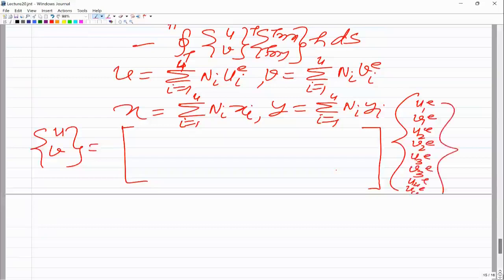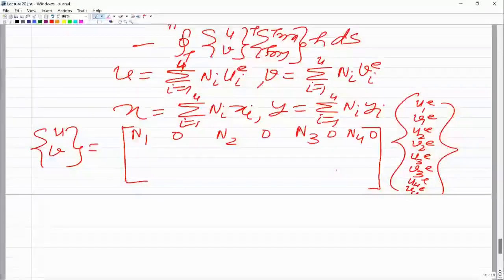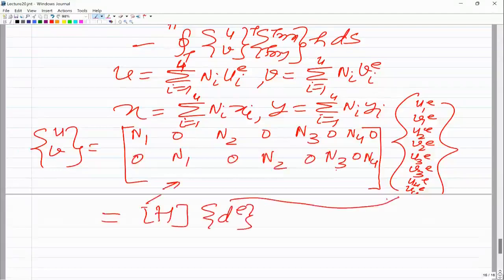And U is N1 U1E plus N2 U2E plus N3 U3E plus N4 U4E. So we should have N1, 0, N2, 0, N3, 0, N4 and 0. V is N1 V1E plus N2 V2E plus N3 V3E plus N4 V4E. So we will have 0, N1, 0, N2, 0, N3, 0 and N4. So this is what you can call your interpolation matrix. So this is H, and this is the vector of elemental degrees of freedom, your DE.